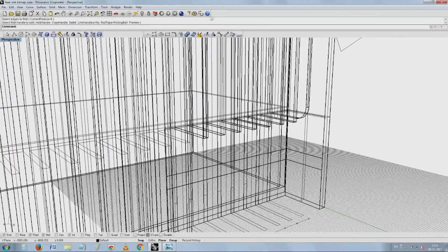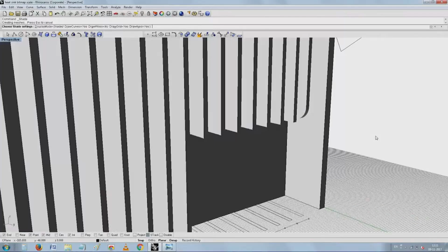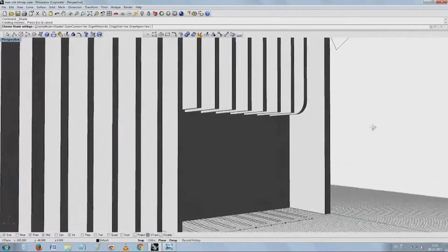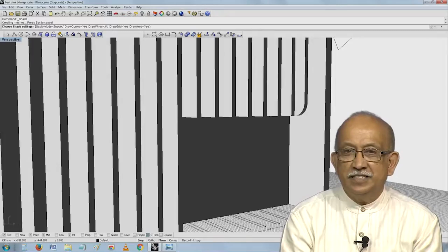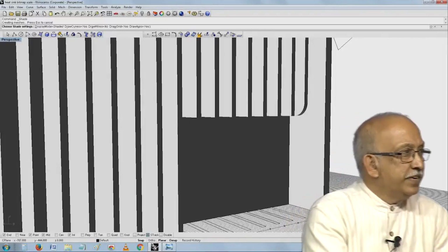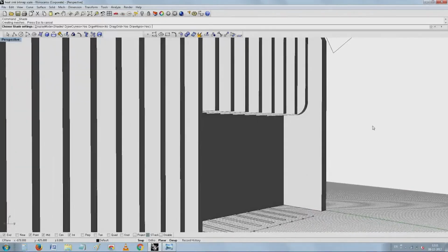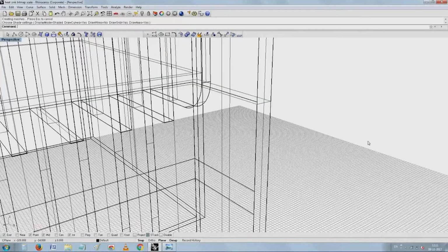See there, it has become rounded, because what I expect is when you are trying to operate a control, most likely we would like to have a smooth rounded edge and not a chamfered edge. So, now I can continue this filleting with all the surfaces that are present here.